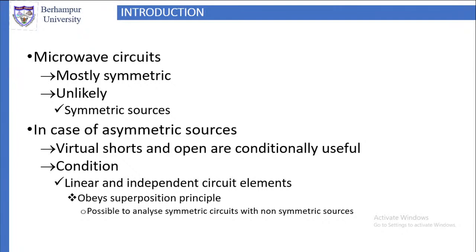What are the conditions under which this will be useful? The condition is that the circuit elements that we are using, except the sources, are linear and independent of each other. The sources also have to be independent of each other.